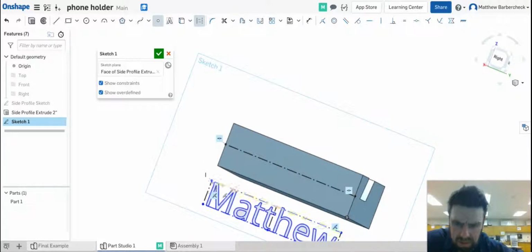There might be another way to do this, but this is what I'm going to do. Up here on your 2D sketch bar, I'm going to hit point. The point button is on. I can now add points everywhere. I can give my whole file chicken pox. All right, but I don't want to do that.